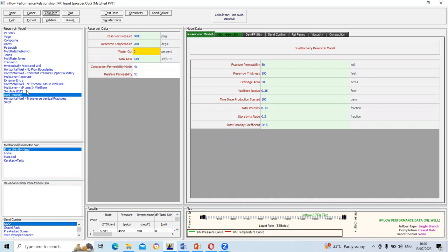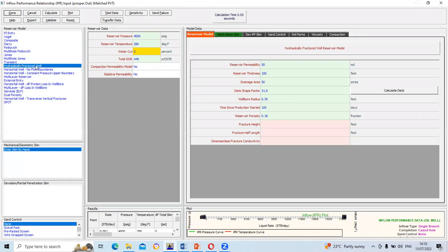There are so many other types of models here that you could also develop. You may have a hydraulically fractured well. That means after hydraulic fracturing, you want to now determine the productivity of the reservoir. You know that once the area around the wellbore has been damaged due to skin, I think we specified that type of skin yesterday as the formation damage. That's the type of damage, because we have perforation damage, partial penetration damage. So that one is just generalized as formation damage.